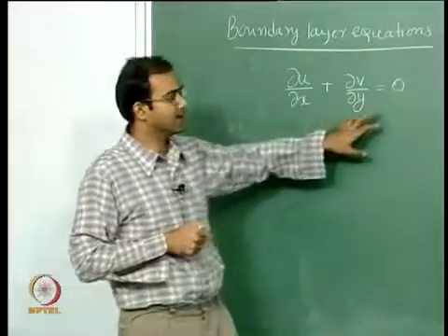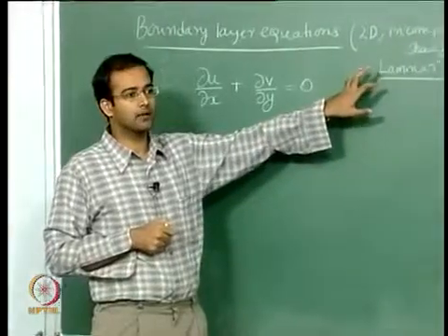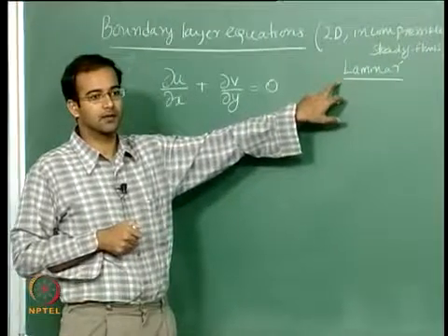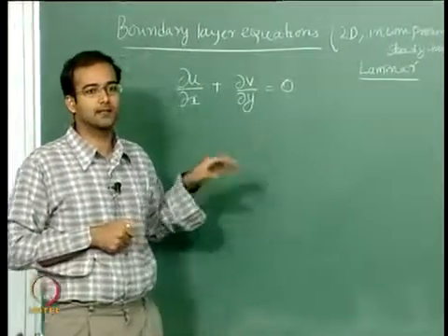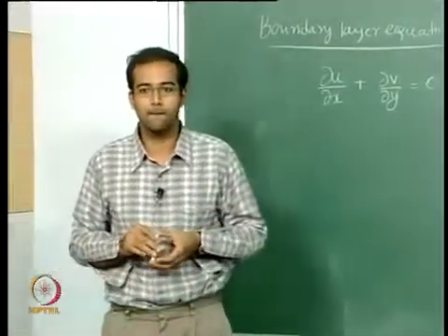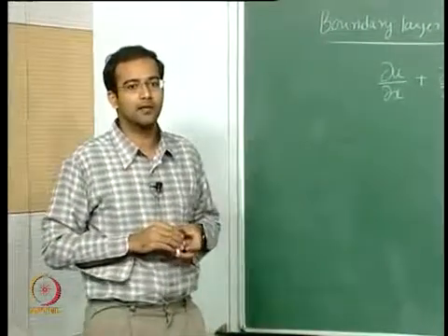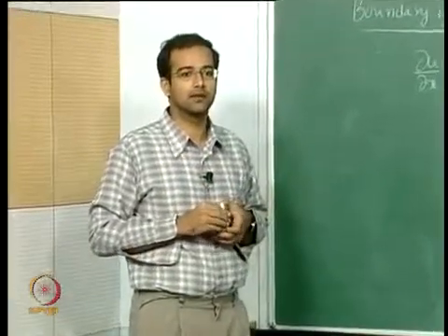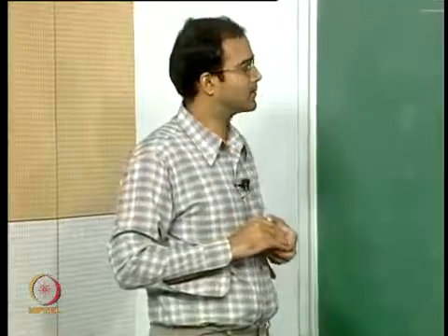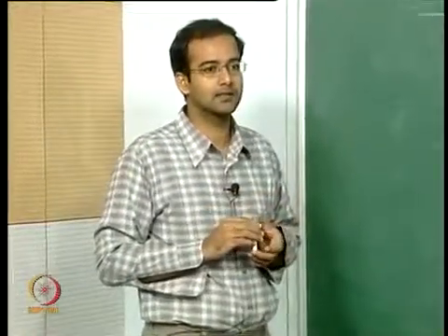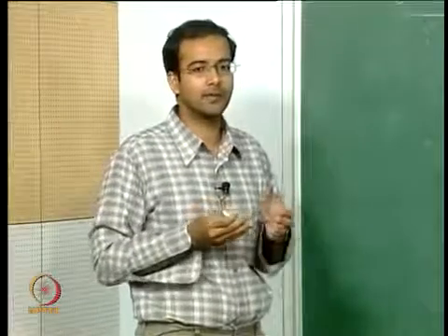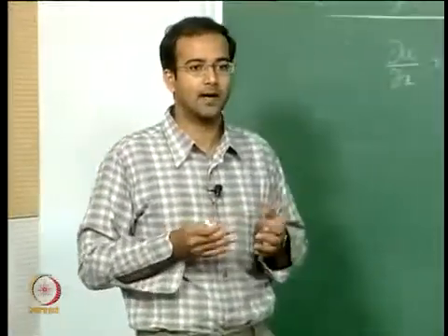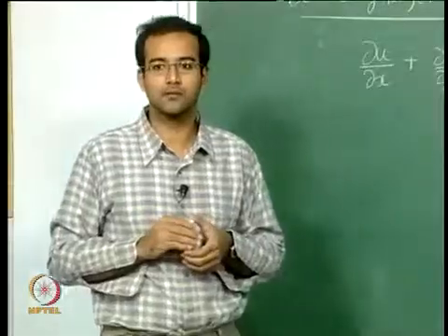So you can say safely that this mostly applies to laminar solutions. When we solve this, the resulting solutions are all for laminar flow. For turbulent flow the characteristics become a little different, and therefore we have to solve the RANS equations, and most of the time you do not have analytical solutions. You have to solve them numerically, but a few extreme cases have analytical solutions which we can do.